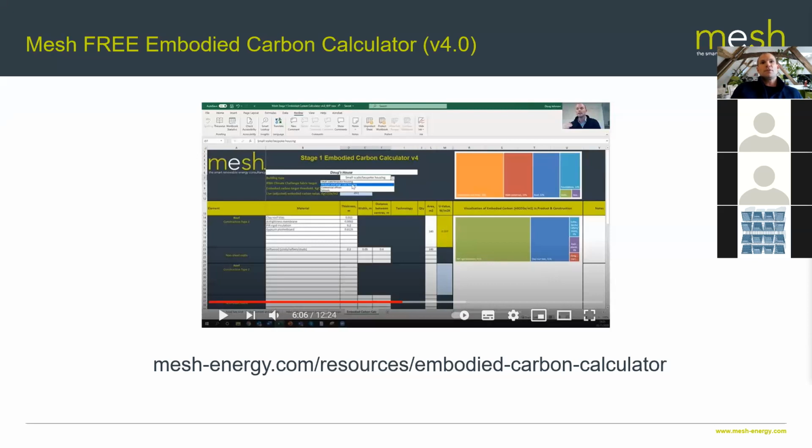Obviously, they come in fixed thicknesses. So if you can't get the U value you need from 300 millimeters of straw bale, then you probably have to add another one, which might be 600 millimeters thick. They're like big bricks, so you're limited to more finite thicknesses. It's a bit more lumpy in that respect.